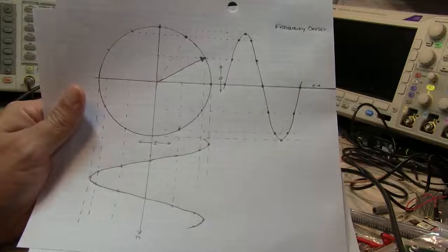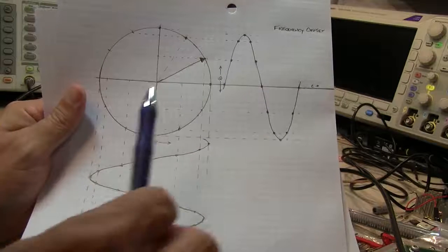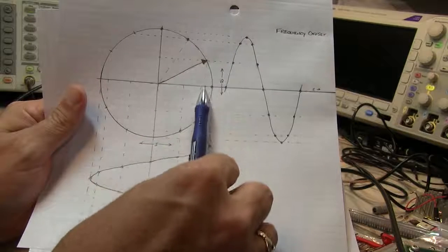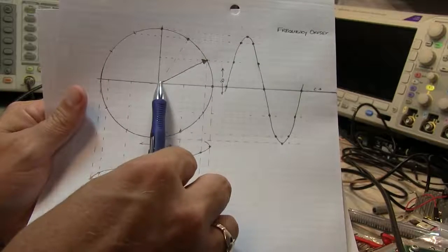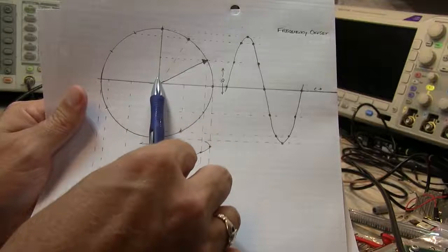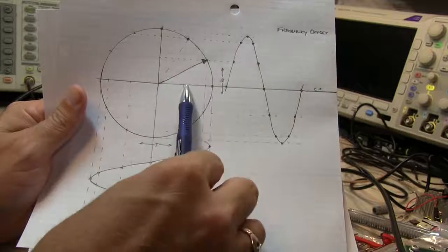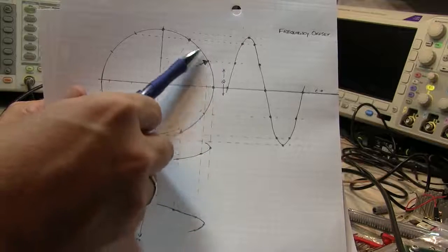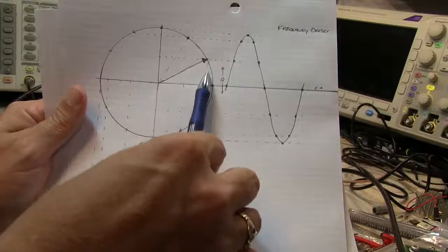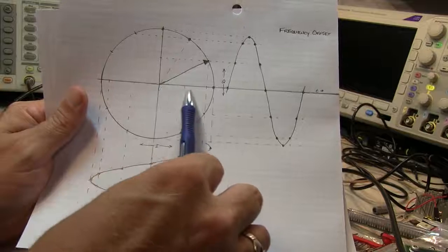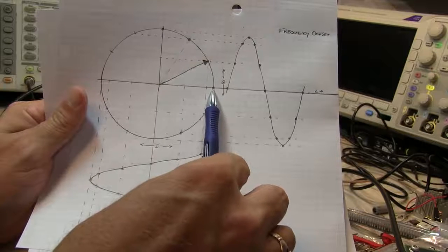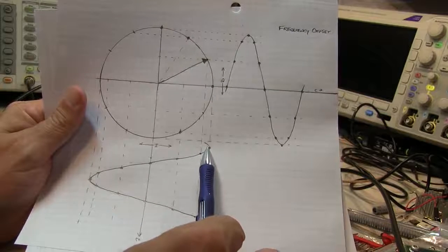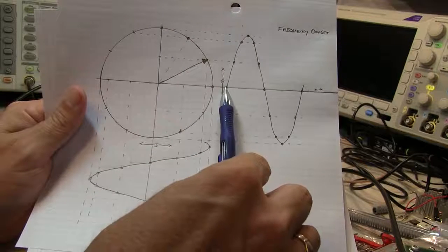So what does that do to our IQ signal components? Remember, the I and Q components are really the coordinates, if you will, of the in-phase and quadrature components of that vector. So if we picture this thing spinning around here, we can pick some points off and say, well, if the vector was sitting right here, the I component will be out here, but the Q component will be right there.